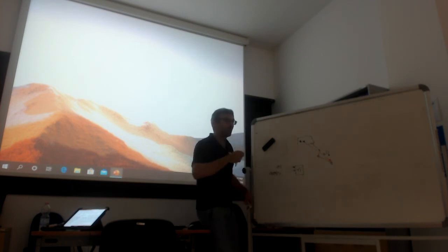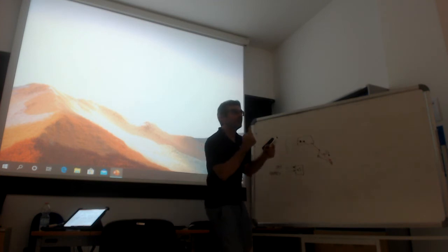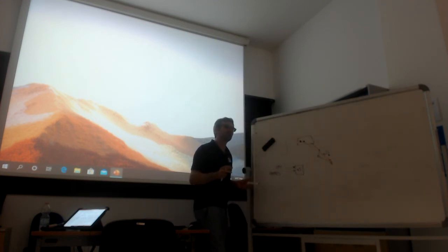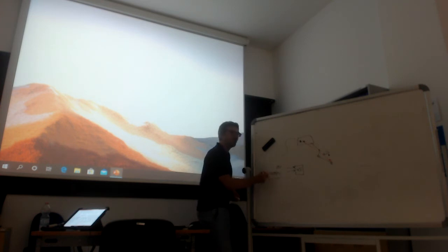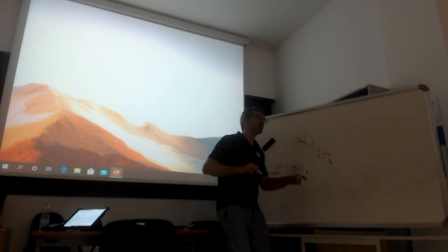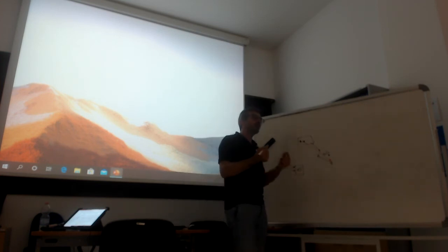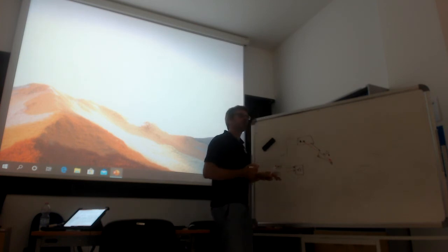Of course, if you have one point foot in contact, you're not able to do much. So this will be dependent on the contacts and how stable they are. Because if you have one foot and the other one sliding, and you get information from both of them, then you get a drift in the estimation of your base velocity.